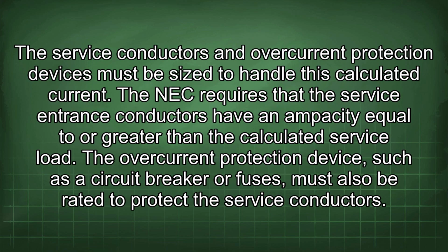The service conductors and overcurrent protection devices must be sized to handle this calculated current. The NEC requires that the service entrance conductors have an ampacity equal to or greater than the calculated service load. The overcurrent protection device, such as a circuit breaker or fuses, must also be rated to protect the service conductors.